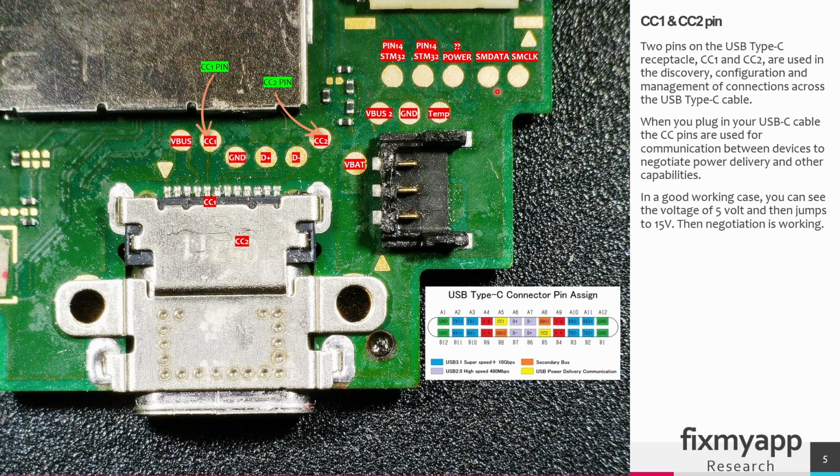After some analysis, I think I know what these test points are. This is the V-bus, CC1 line, this ground pin. This is the differential pair data lines for the USB 2.0. Voltage of the battery is located here. So this is the positive side, negative side. This is the temperature sensor. The V-bus here is also present. So these two are the V-bus voltage. It's the ground. Temperature sensor data goes to this test pad.